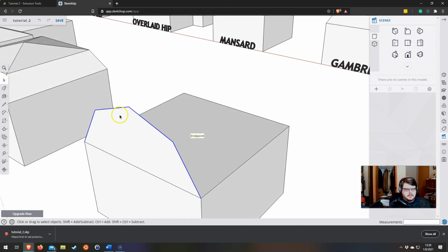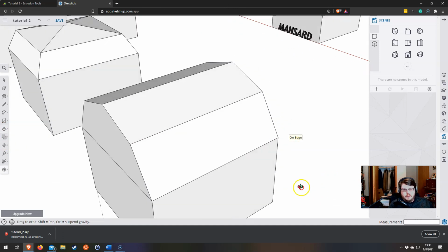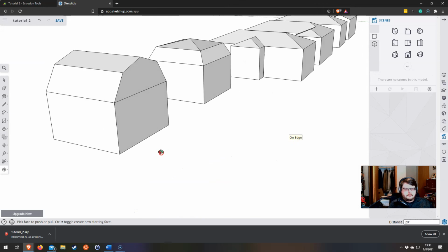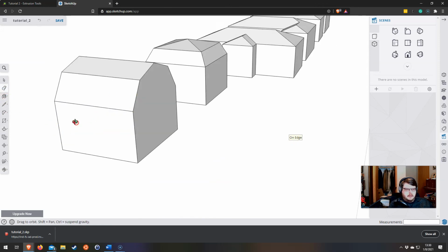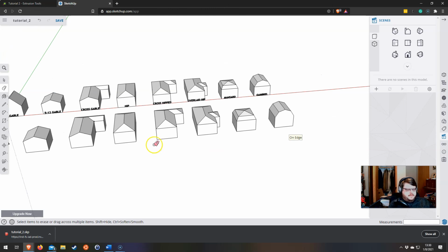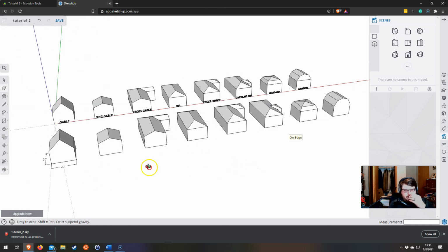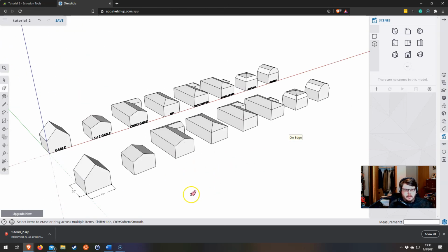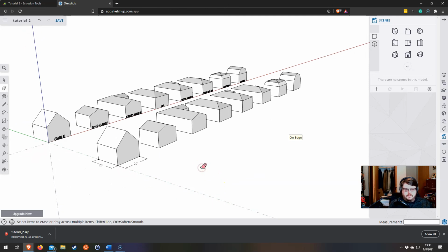So I select it with the select tool, right click on it, and say explode curve. And now it is 4 distinct line segments. You don't see anything happen, but you will when you push-pull this to here and infer to that outer edge and end up with this nice clean roof line. And that's it. A bunch of roofs. Simple, great way to demonstrate construction geometry and the basics of 3D modeling in SketchUp. And we'll see you in the next tutorial.